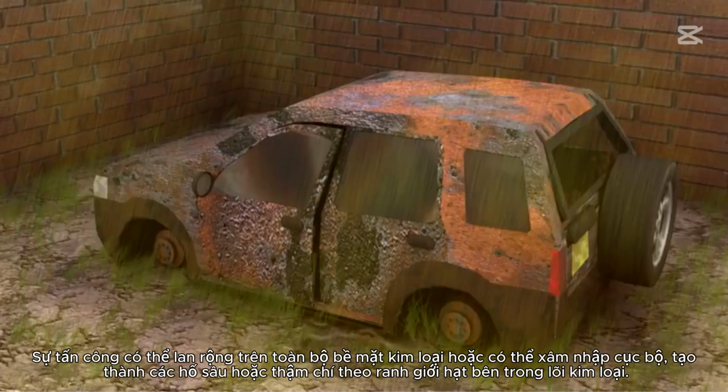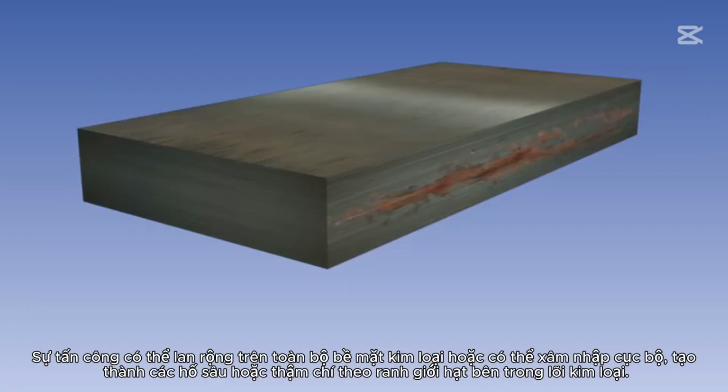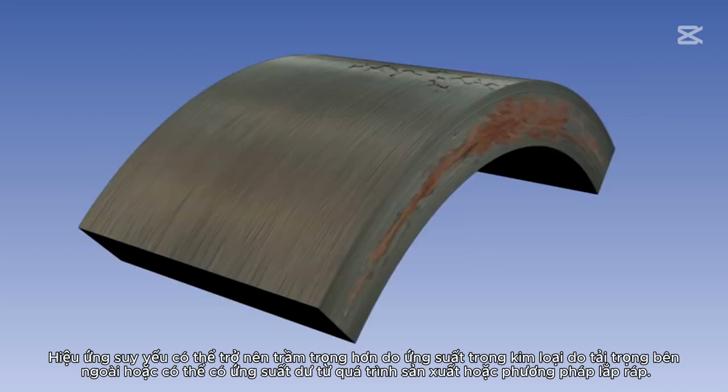The attack may extend over the entire surface of the metal, or it may penetrate locally, forming deep pits, or even follow grain boundaries inside the core of the metal. The weakening effect can be aggravated by stresses in the metal due to external loads, or there may be residual stresses from the manufacturing process or method of assembly.